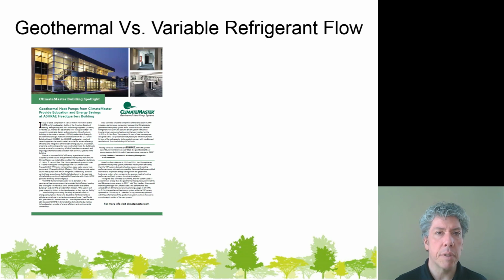So geothermal is this idea that we take thermal energy during the summertime, stuff it into the ground, and in the wintertime, pull it back out. That's what geothermal is all about. There are several different geothermal type systems. You can do what I want to do at my property, which is drill holes into the ground about 200 feet, run pipe through it, and exchange heat with the ground at that depth.